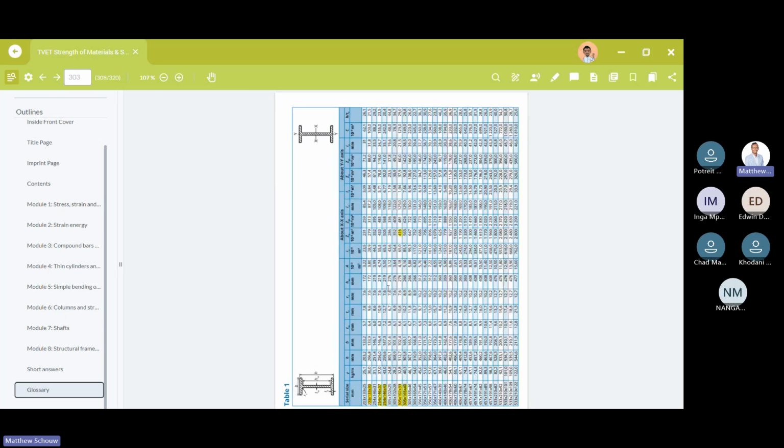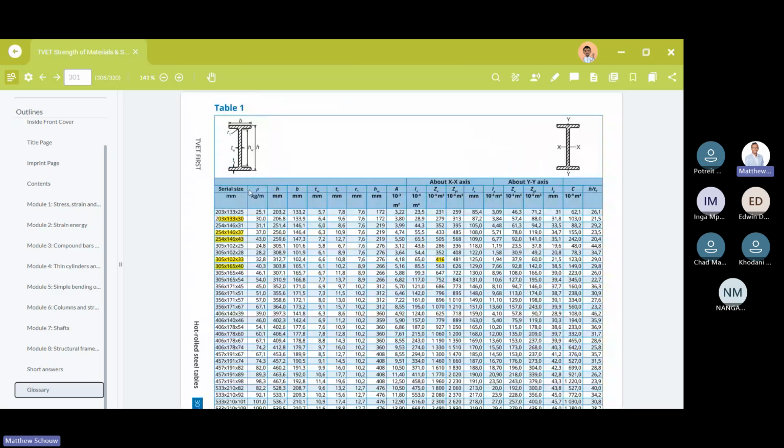Okay, here we go. So these are the steel tables, right? Edward, particularly you. Over here, for the first half, we have all the geometric properties or dimensions of the beam. Are you with me? And then area we essentially get over here, and it tells you the unit. So I believe we're looking at a 254 by 146 by 43, if I'm correct. And you notice the area there would be 5.5. Are you with me? That should be the area.